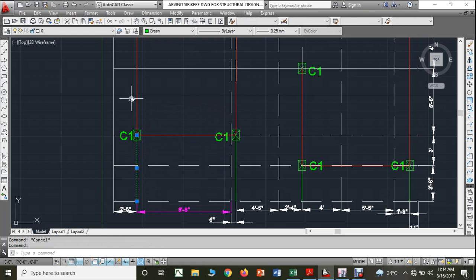Okay, so when I check this beam and this beam, usually when cantilever beams are casted, that beam will be casted along with this beam. So usually we cannot maintain different depths of the beam. Okay, we cannot maintain that. Therefore, usually what we will do is maintain the same depth, whichever is greater. According to these two, this will give you the more dimension. Therefore I am maintaining this depth to this only.